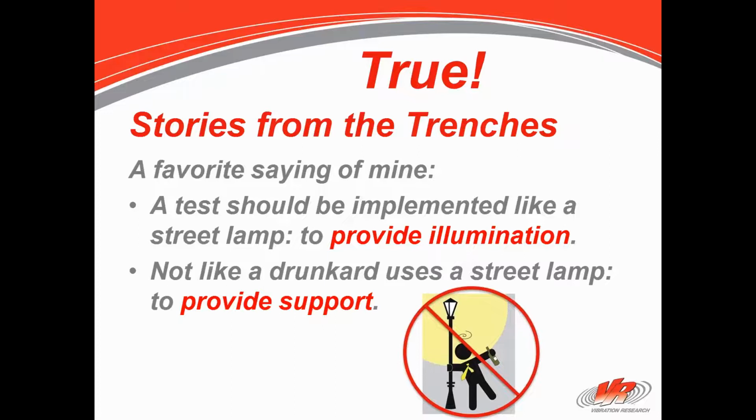Typically when people are setting up a test, they're probably first doing a sine test, and everyone focuses on the sine test and does a sweep and hopes that it works. What you can do is just run a low-level random test on it, and the Vibration View software actually has ways to do that with low-level startup, where you can just get transfer functions of all your accelerometers and get an indication of what's going to happen. It will even tell you what is the highest G calculated to come out of that accelerometer. And you can look at that and, as I said, make sure that the cables are all working properly, you don't see the big spikes, and that everyone is happy.